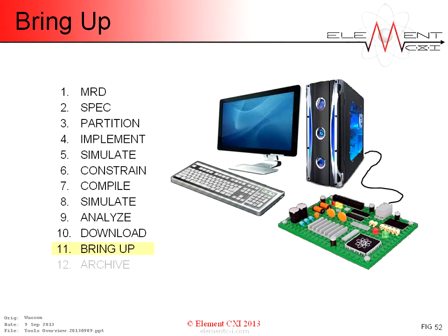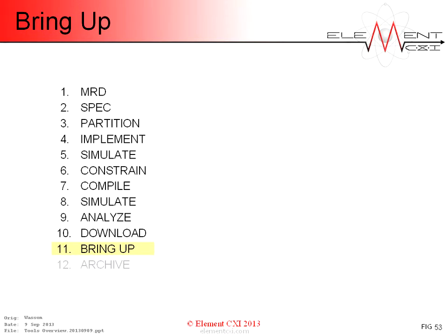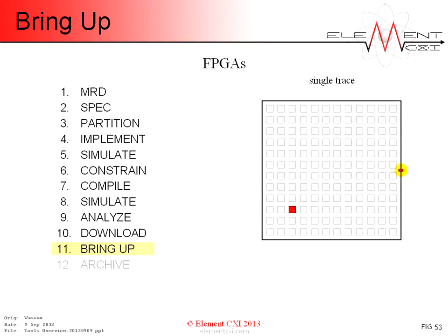Debug tools also need to embed analyzers with programmable triggers and capture transient data. Performance tools should be able to monitor, analyze, and report on data stream behavior and attributes. In the early FPGA days, we used to route single signals out of a device pin to a PCB test point, kind of like a hardware printf statement.